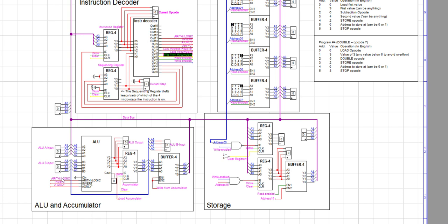So you've got things like arithmetic, which will be the same values as this arithmetic logic wire. Even though they're not physically connected, they're connected through the name. So whenever this invert gets changed to 1 or 0, this one will keep the same value. And then we've got this storage. So whenever we're done with the add or subtract function, we'll store it in this register right here.